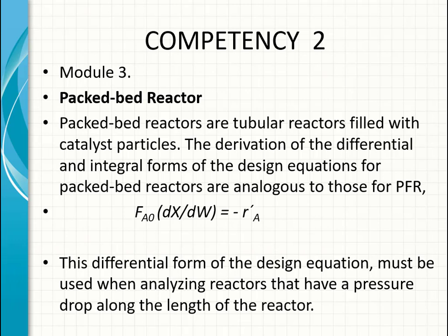Packed bed reactor. Packed bed reactors are tubular reactors filled with catalyst particles. The derivations of the differential and integral forms of the design equations for packed bed reactors are analogous to those for the PFR. So here we have the expression for packed bed reactors: Fa0 times dx divided by dW is equal to -ra prime.